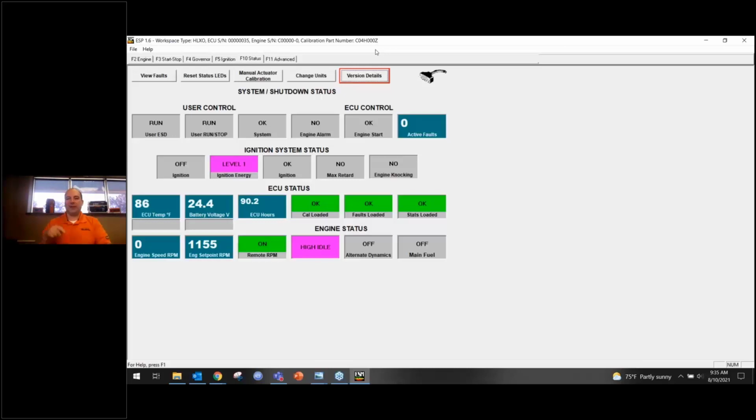But you look in your program files and it lists 2, 3, 4 active ESM ESP sessions. Well, each one of those is for an ECU that you disconnected from but didn't close out the right way. This can cause a bit of a nightmare when you're trying to upgrade your software, because it says, no, I can't upgrade. I'm currently attached to another engine. Even though you're sitting in your IT department, your guy's going, yeah, there's nothing here. You have to close out each of those individual sessions before it would allow you to update your software.